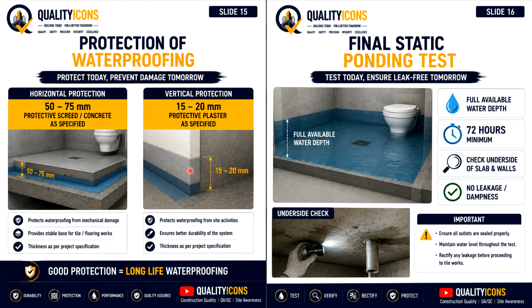Coming to protection of waterproofing. Once the waterproofing coating has been completed, you must protect it. Waterproofing can easily be damaged by subsequent construction activities. Horizontal protection may be provided using the specified protective screed, protection plaster or concrete, typically shown here as 50 to 75 mm, subject to project specifications. Vertical protection may be provided using protective plaster, typically 15 to 20 mm, again as specified.